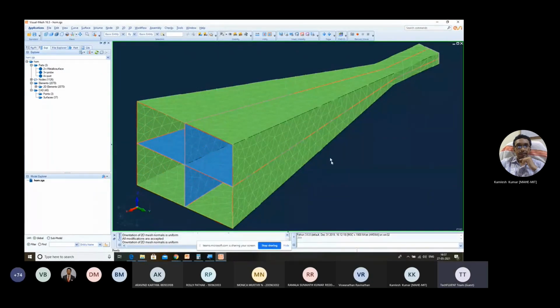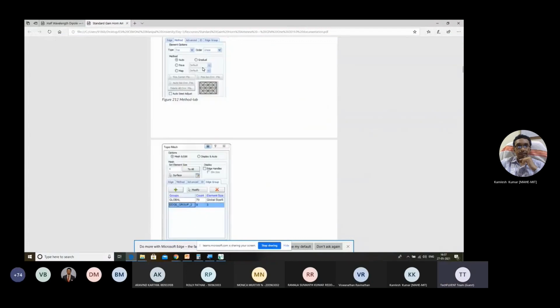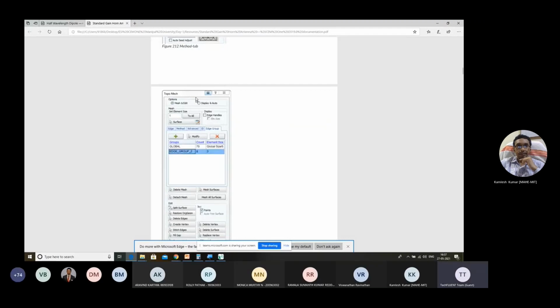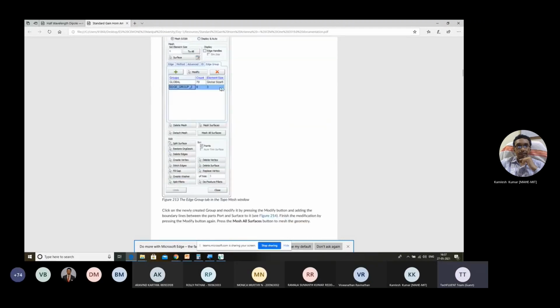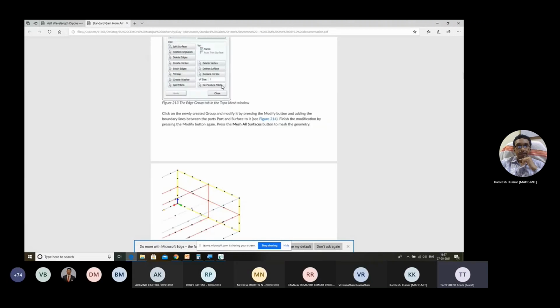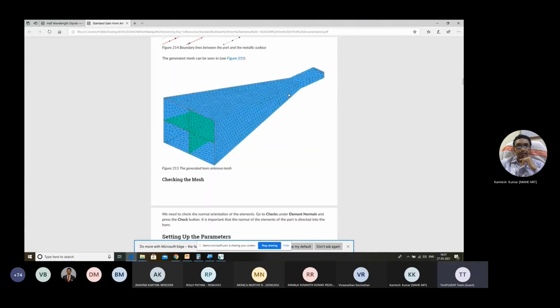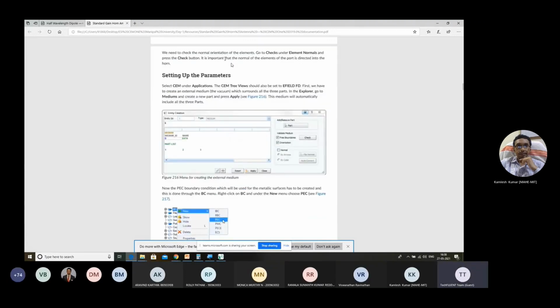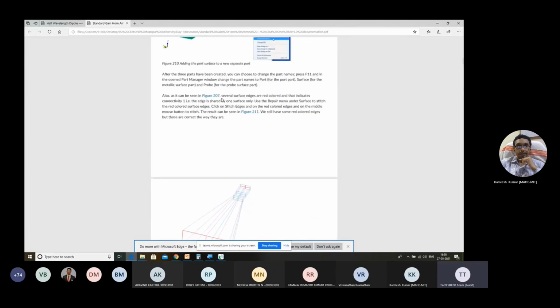Now we can go ahead with our SEM window. Just click on the SEM window. You can also cross verify how exactly it goes about. So the meshing operation: here we went with Topo Mesh 6 mm, given the edge also like 3. We have selected all these edges. We have refined the mesh. And now we have to go for the parameters, all the parameters. So this is for the SEM window. Until this part, whatever we have done, it's absolutely the same.